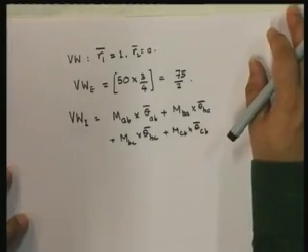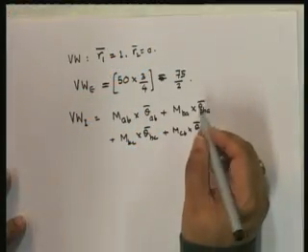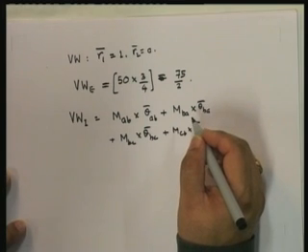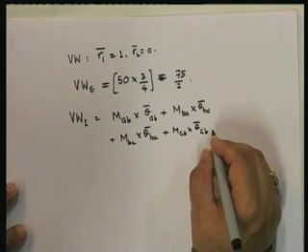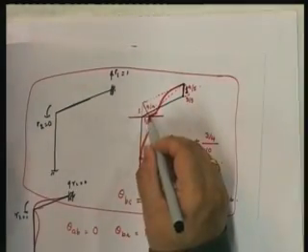The only thing left behind is the load 100, which gives rise to reactions at the supports. What kind of reactions do I get? The reaction that I get is 50 and 50 vertical in both directions. I just have to find out the work done by each vertical reaction. Is this point moving vertically?